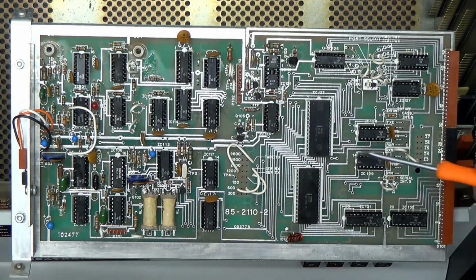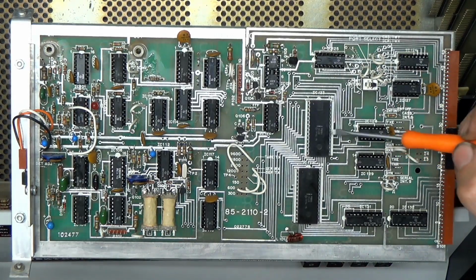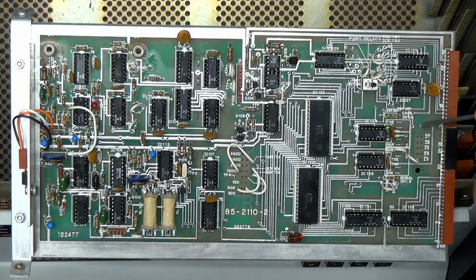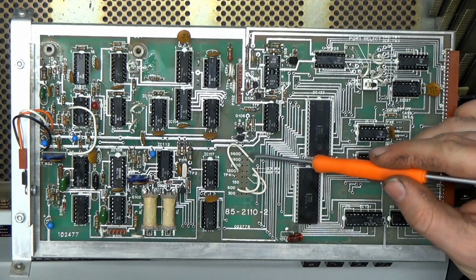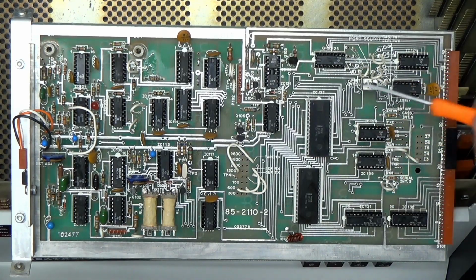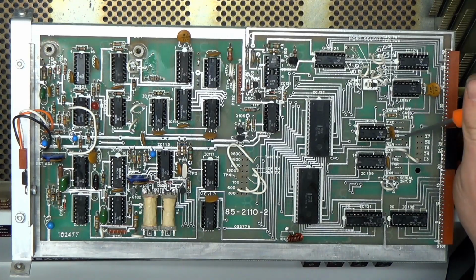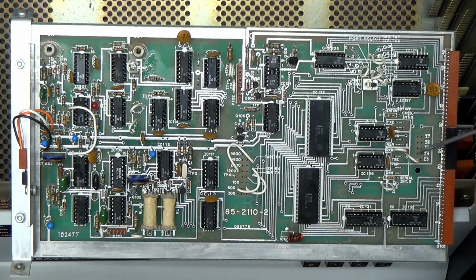It has a pair of 8251 UARTs on it. All of the configuration is done with soldered-in jumpers, as Heathkit liked to do. That bothers me. As we mess with this and try to get it going, I'm going to take these jumpers out. I'm going to solder pin headers into all of these jumper holes, and then we can wire wrap between them, and it'll be much easier to change the configuration of the card later that way, I think.